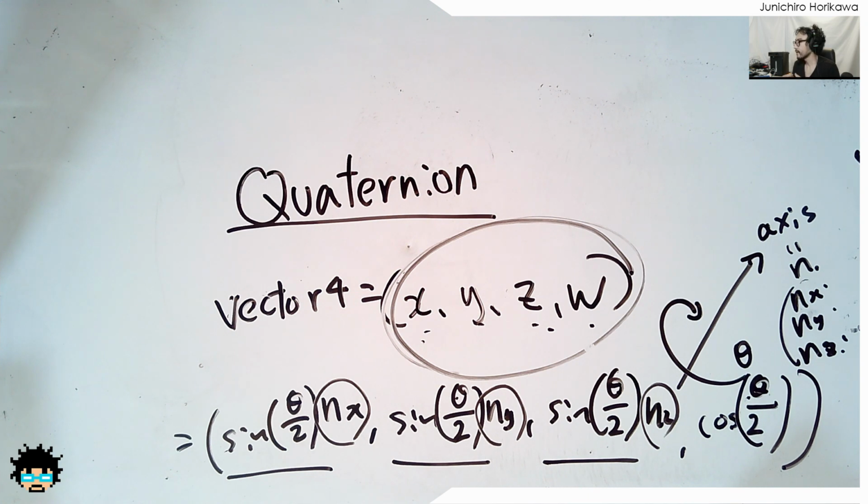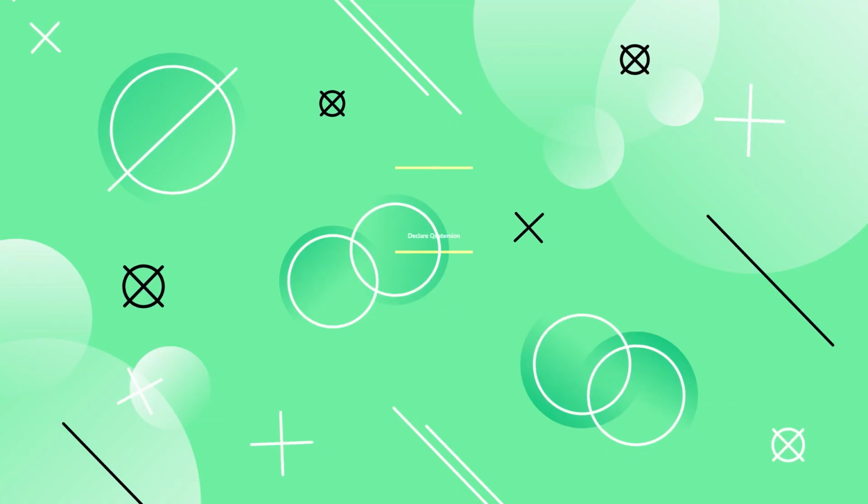Now, as I have just told you, what I mean by rotation is that you can rotate the vector value from one point to another point using an axis and the rotation angle. A vector can sometimes be a directional value, sometimes a positional value. You can rotate both of the values using this quaternion. And let me show how exactly you can use it inside Houdini with some examples.